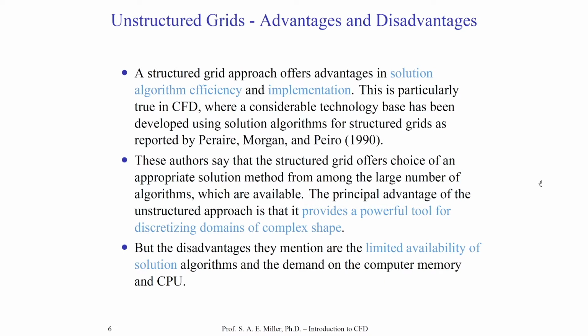There are many, many more solution algorithms for structured meshes than there are for unstructured meshes. This is one of the principal advantages of the structured approach. Of course, the unstructured approach has the biggest advantage of all in terms of creating the grids for complicated geometries. That is, if I have a very complicated boundary, for example, any type of part in engineering, complicated combustion chambers, the human lungs or heart, the basin of a river, it's very hard to have a structured overlapping mesh.